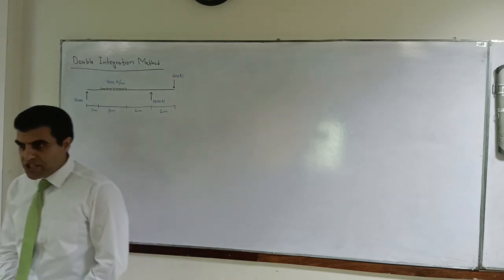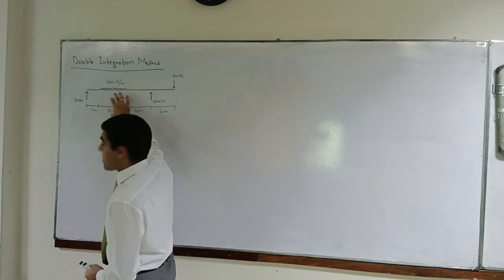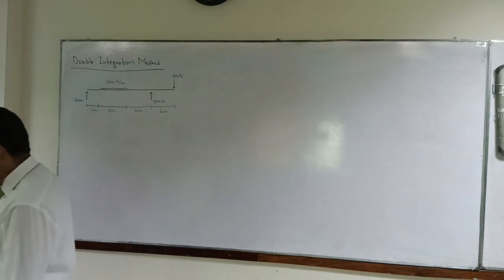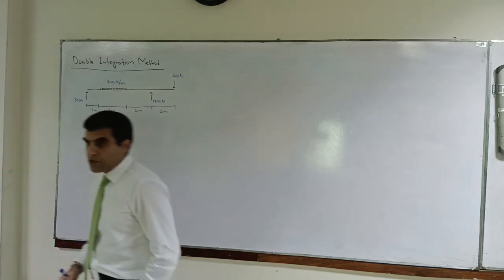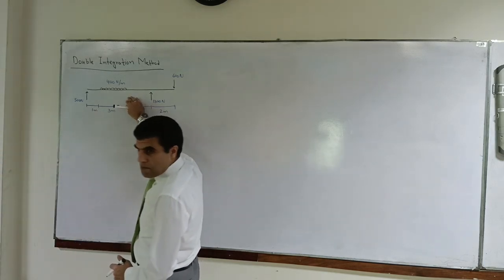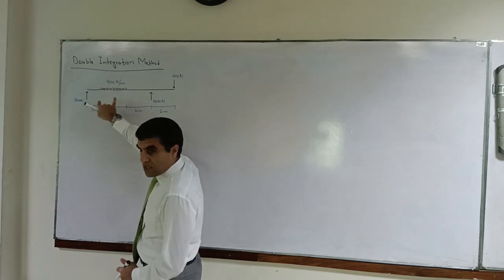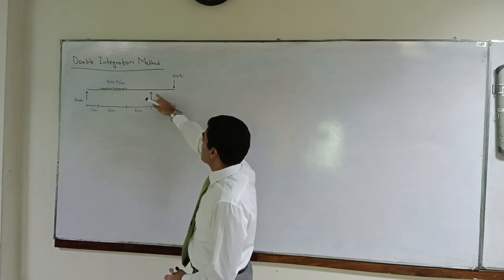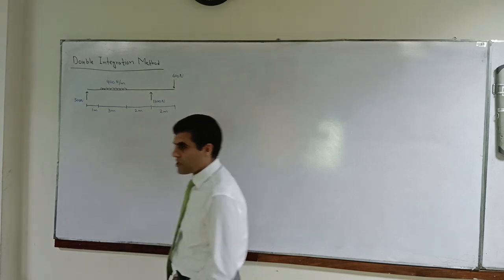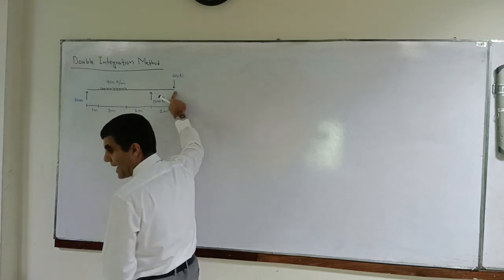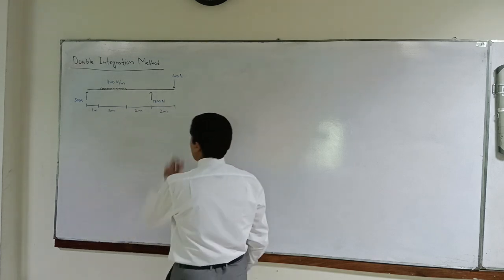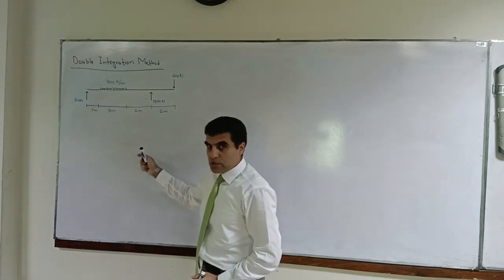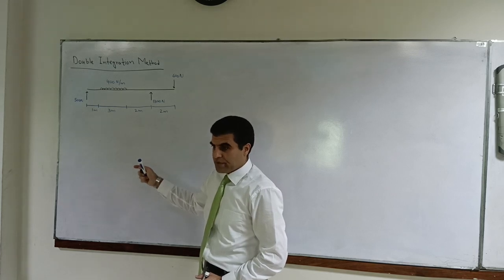I was asked in the previous question how could we do the uniformly distributed load using the double integration method. That's why I will work out the moment equation for you. So this is a beam, okay, which has got a UDL. It's a patched UDL or partially applied UDL. It's cantilevering out and subjected to a 600 Newton load at the edge. So now, how can we work out the moment equation?